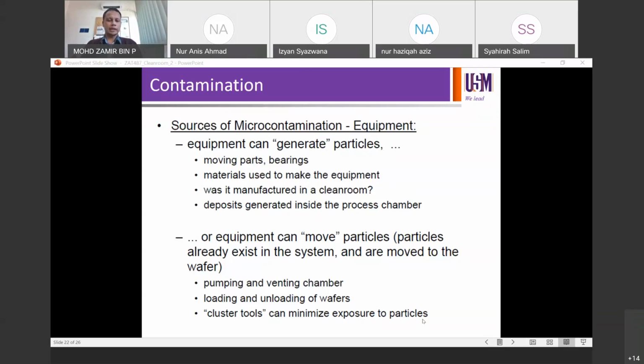When I started last time, I started as an equipment engineer. I worked on the TEL track system to do all the coating and deposition process, to do with the resist spinning and everything. I'll talk to you later about the process. But yes, we have so many PMs that need to be done to make sure that we don't generate particles unnecessarily on the wafers due to the residues and quality of the equipment.